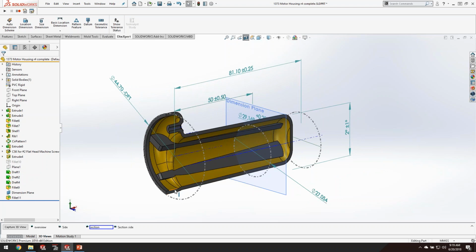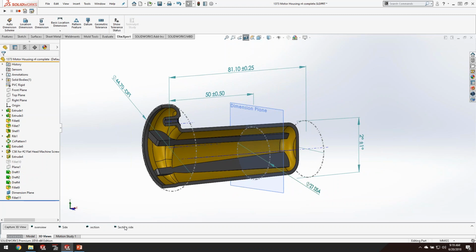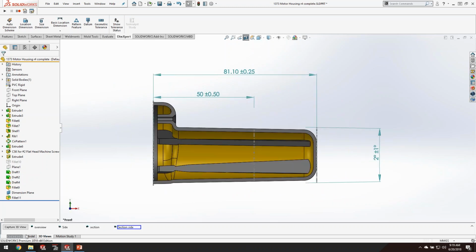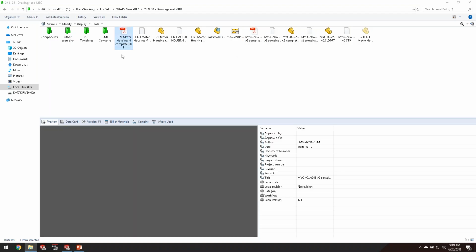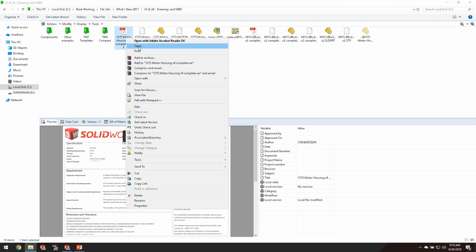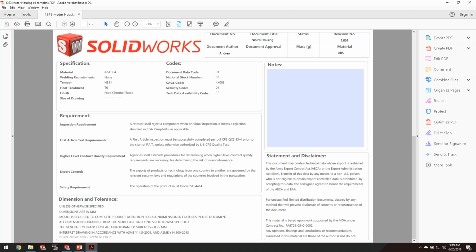So to save and store this graphical information so that it can still be rotated, we can look at it, see exactly how it's behaving, see different orientations of the model with all the critical dimensions. But then we'll actually export this information using the SOLIDWORKS MBD utility, adding notes to our fields and our callouts and so forth and so on, but generating what's called a 3D PDF. So this 3D PDF is just a PDF then that can be used to view the output. So we'll take in, we have our nice title block in here.